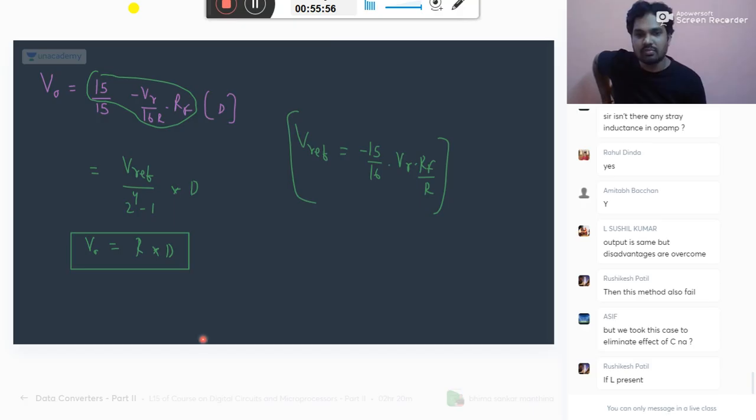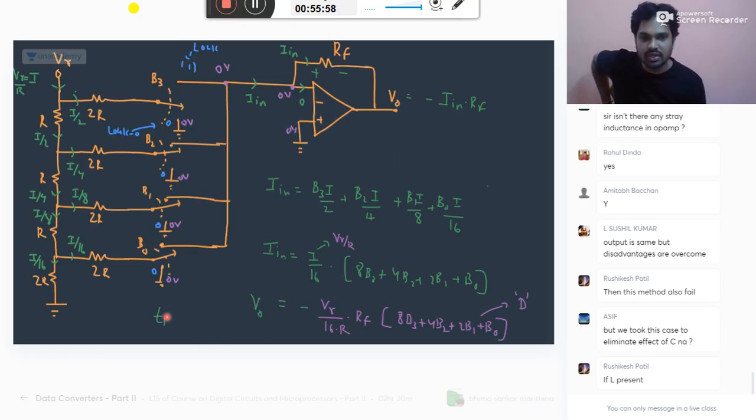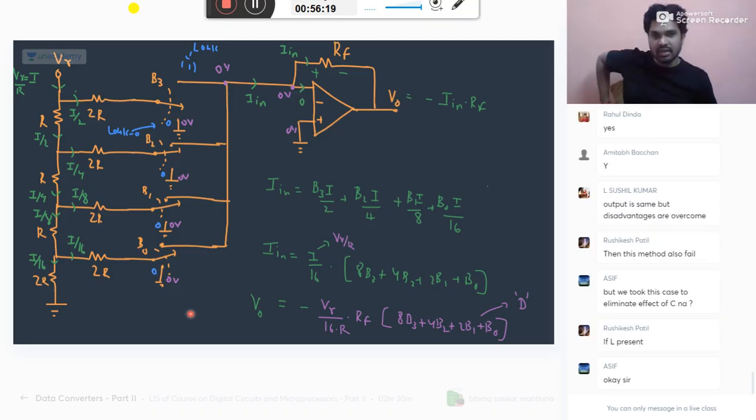Every time, propagation delay is very important. For the propagation delay of the circuit, mostly we take care of the RC time constant tau only. This is more dominant in the circuit. That is input charging requires. Who is stopping that input charging? It is generally stopped by the capacitors.